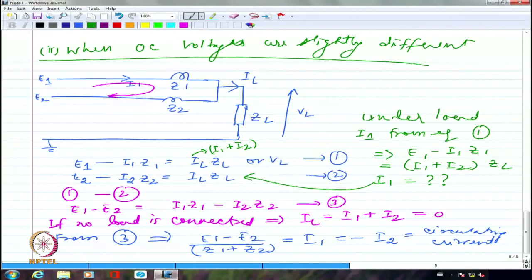Only thing is, if I am sharing a load of 120 kVA, I would like the 100 kVA to take 80 and I would like the other transformer, 50 kVA, to take 40. Whether I am actually looking at the load division in proportion to their rating, that is what is very, very important. 100 kVA should take the lion's share, 50 kVA should take a lesser amount. And that's what should happen ideally if the impedances are comparable, right?